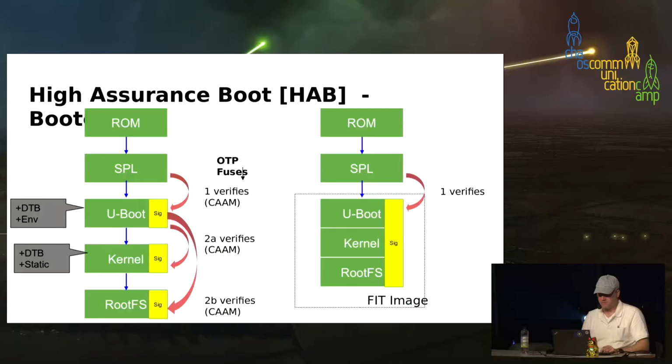And also, once the kernel has been verified, we can also verify the root file system. The root file system, if you compile it with Yocto, is maybe 10 megabytes minimum size. If you use a minimal or a small Debian setup, you can reach 120 megabytes. But still, it's a very fast process.